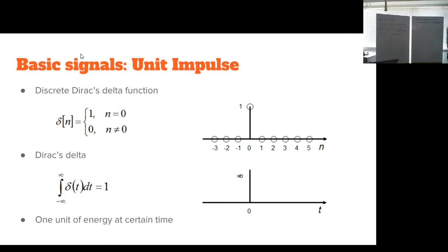Digital systems are basically defined by the impulse response. That's one way of defining them, and that's the most important way of defining. Since basically if a system is linear, I'll go into linearity later, then you can find out what the system does by just taking the impulse response, meaning you feed in an impulse and see what comes out. You know exactly what is inside of the system.